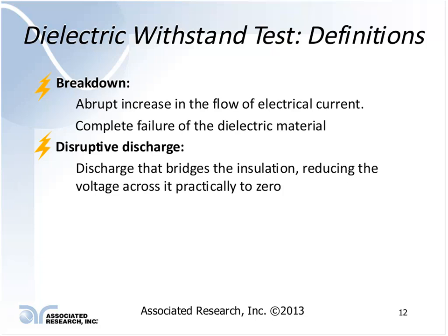Let's say I run a Hipot test on a solar panel, and it says breakdown, and I get a breakdown at, let's just say, 1,000 volts. I run the test again, and again I get a breakdown. This time it's at 200 volts, and let's just say for the heck of it, I run the test a third time, and now my breakdown's happening instantaneously. That's a pretty good indication that you actually have a true breakdown because your insulation has been compromised, it's now a conductor, and it's breaking down immediately. There's not even a voltage buildup this time, it's just a short circuit path.